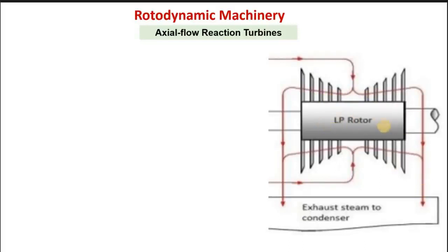The flow is divided into two halves, and the axial thrust is divided into two halves also. And also the height of the blades will not be too high in both directions, because total m dot is divided into two parts, right? Compared to the previous scenario which we have seen before, that all of the fluid was flowing in one particular direction. But now in this case, all of the fluid is divided into two halves, so m dot is divided into two halves.